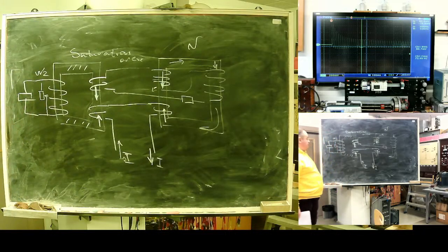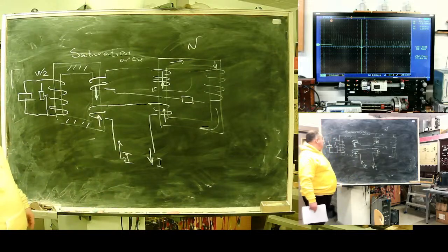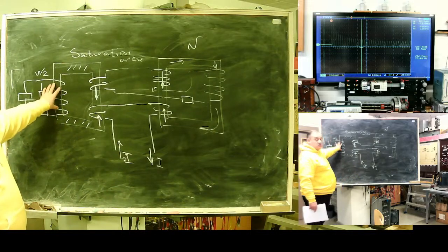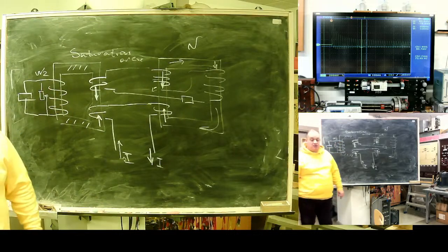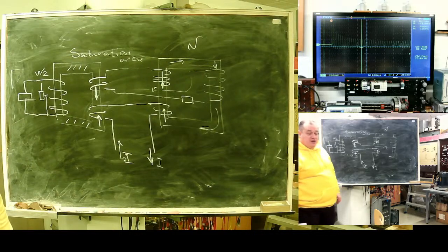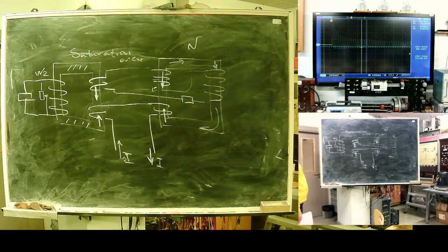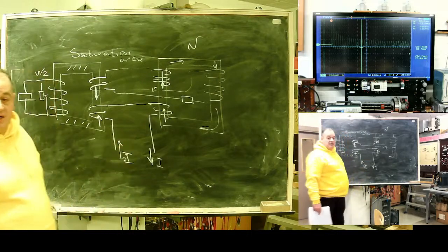In case this differential current increases, current through this coil increases, and the relay trips. Everything works fine. If you assume pure sine here, this is the relay current.